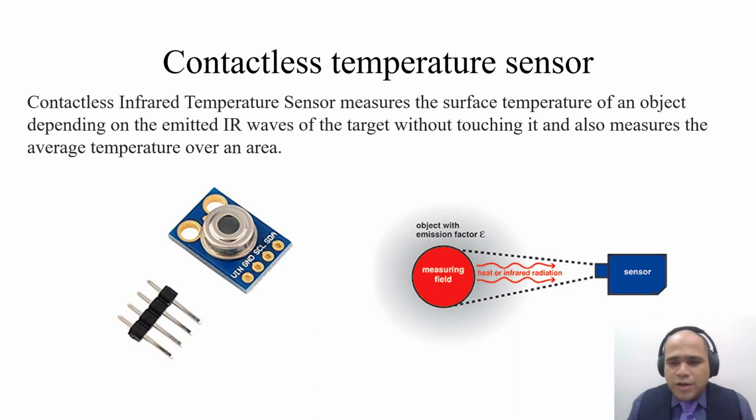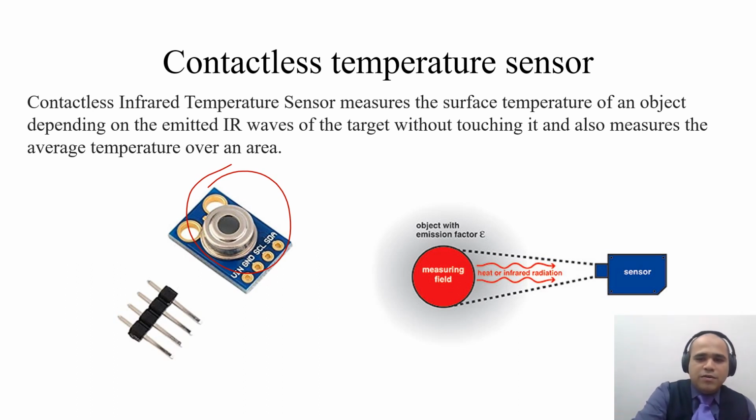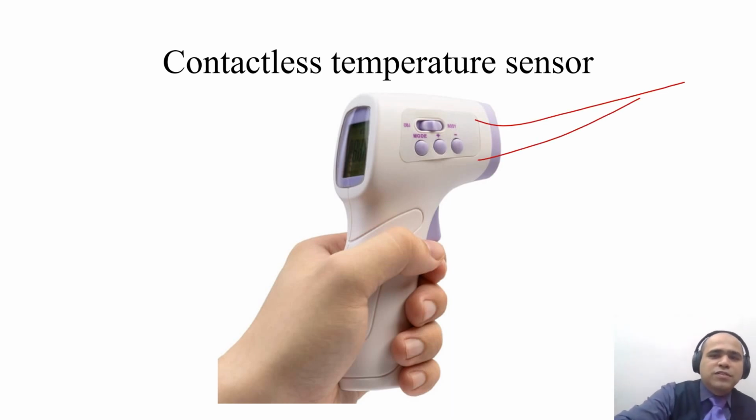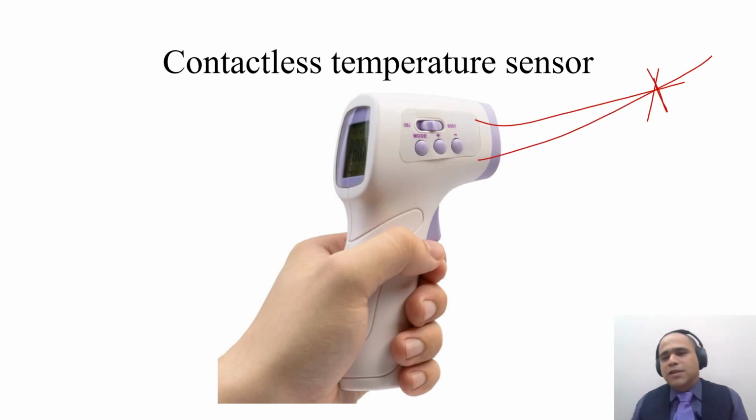Nowadays, because of COVID, nobody is going to measure temperature with a regular thermometer. So you can see policemen or people at the entrance standing with a temperature gun, and that gun uses a contactless temperature sensor, which is nothing but sensing the IR heat radiated from the body. They put a gun with laser alignment onto your head at the center and try to measure the temperature over there. The obvious application of the contactless sensor is this temperature measurement gun, and it also has a laser focusing. So whenever that focus happens, it measures temperature at that point.